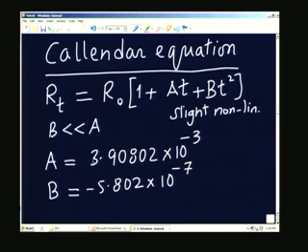You see that it is going to become more or less as big as this term. Okay. So, at high temperatures, when you are using the PRT over an extended range of temperatures to be measured, it is necessary to take into account the nonlinearity. But how are we going to take the nonlinearity into account? That is what we are going to look at now.